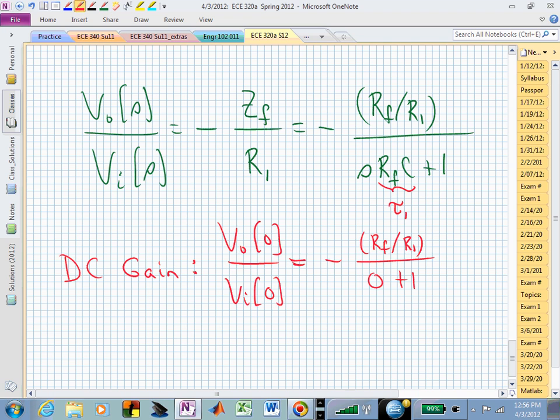And what does that tell us? That actually tells us the level that we're starting at in absolute terms. If we convert it to decibels, we would take 20 times the log of that number, and that would be where our Bode plot begins. Then it will be flat in our straight line approximations until we reach the break frequency, which is our pole. That's why we might be interested in the pole location.